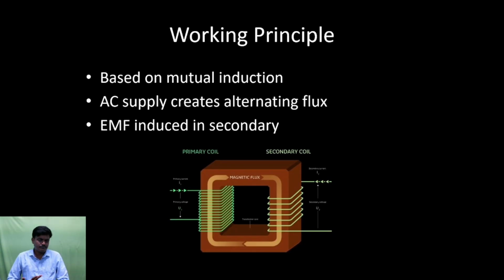By means of that useless flux, suppose that flux links some nearby iron conductor or copper conductor, it creates some voltage or current value. First of all, it induces voltage. If a closed path is there in the conductor, the current also flows. That is called eddy current. That is a wastage of current, absolutely a waste. That's why we call it eddy current loss.